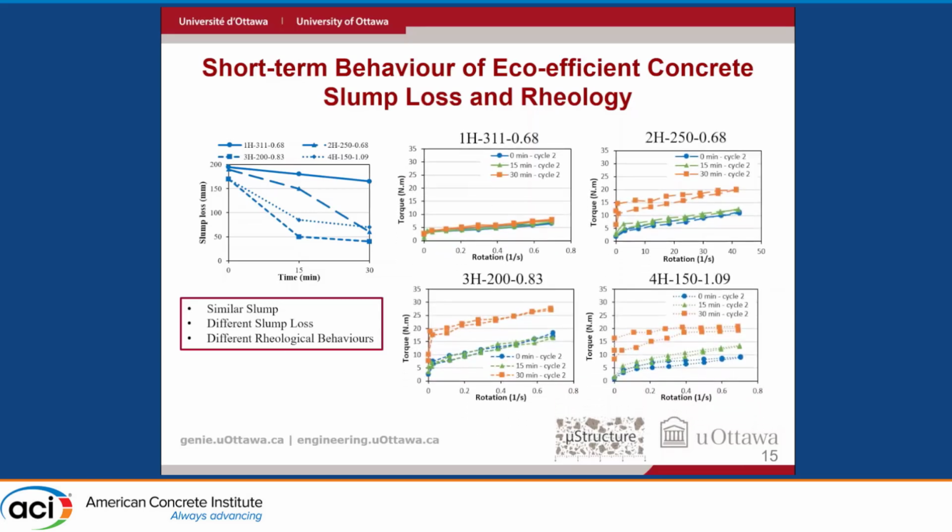So we have a rotational rheometer in-house, and we were able to test torque as a function of the rotation for all of those mixes. So here you see the ACI mix. Here you see our 250, 200, and 150.